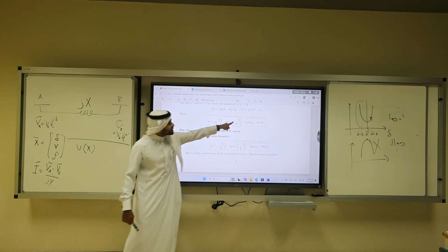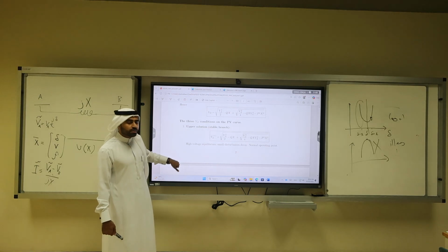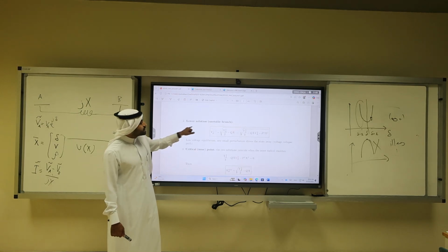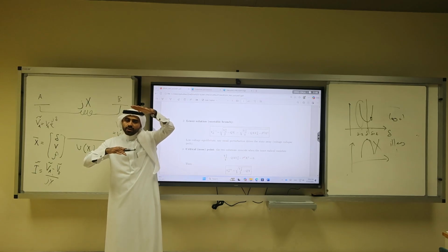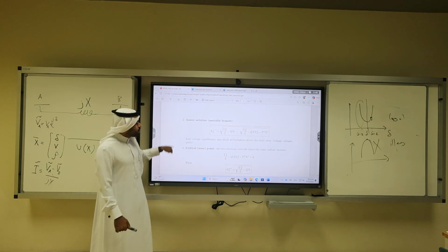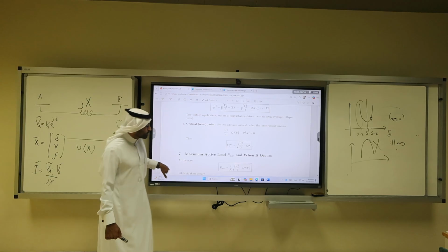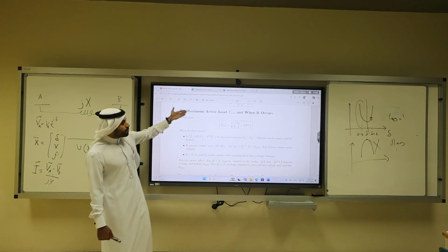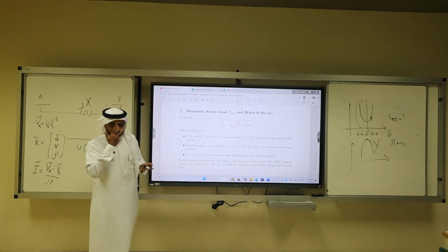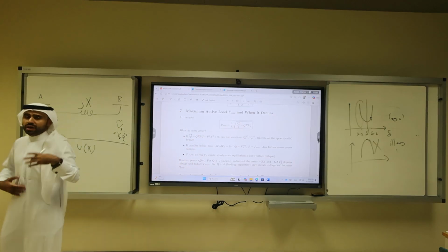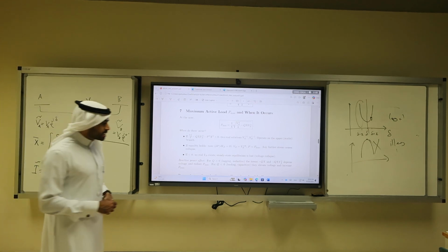Now, if you take the plus sign, you will have VB plus, which we will call the upper solution. If you take the lower, this is the unstable branch, the lower voltage. You always want to have the voltage as high as possible, close to 1 per unit. Or the nose point, which is just this number by having this term be 0. So the maximum reactive power, or real power, should be in this equation. I'm not going to ask you to memorize the equation. You will have an opportunity to create your own formula sheets when we have the exam.